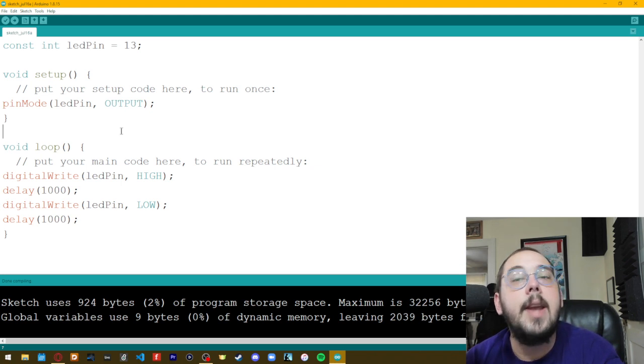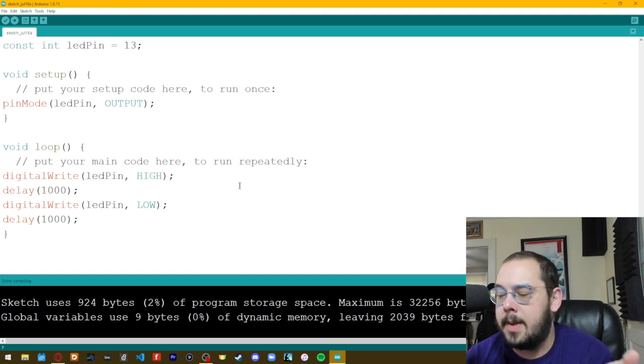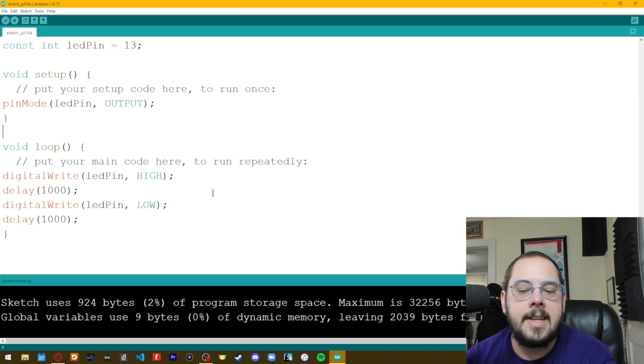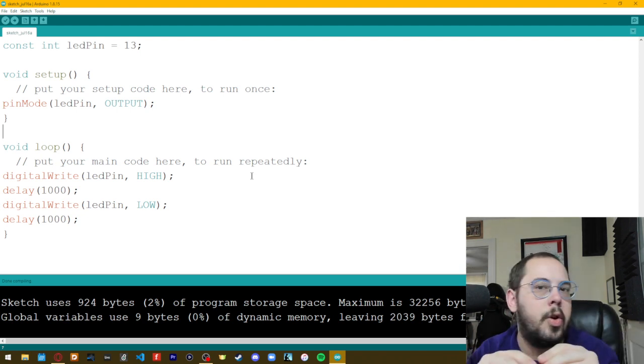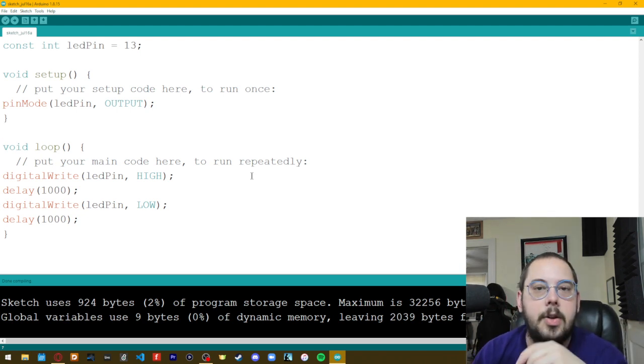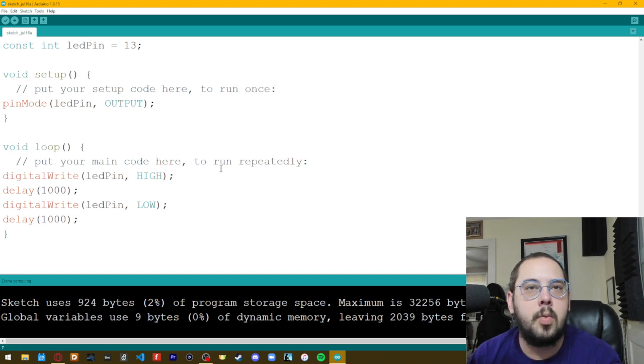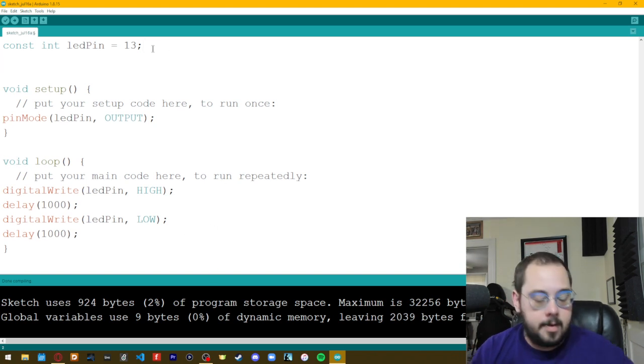What I want to do next is now add in a digital input. So the digital input, as we'll see, are any digital signal that is being received by the Arduino. So it is sending that data, or that electricity in, and the Arduino is responding to, is there electricity, yes or no, on a certain pin. So to do that, I think a button or a switch is pretty straightforward. So let's work with a button first.